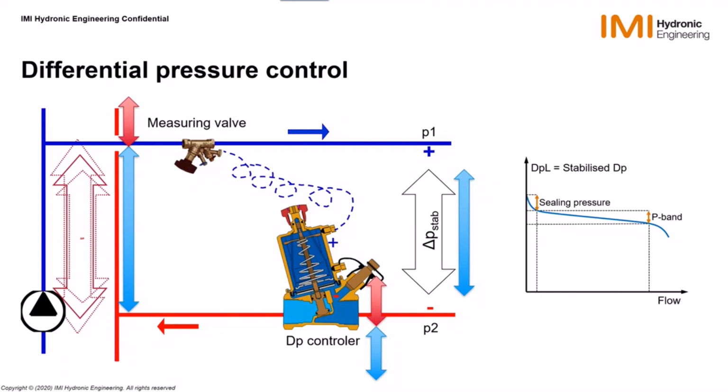And then you get the ceiling pressure, and this is all about the ability of the delta P controller to go correctly and fast to closure when the load is closing, and to go actually faster than the load, otherwise it would let the whole available differential pressure go on the load. So we get this essential element in mind now for what is differential pressure control.